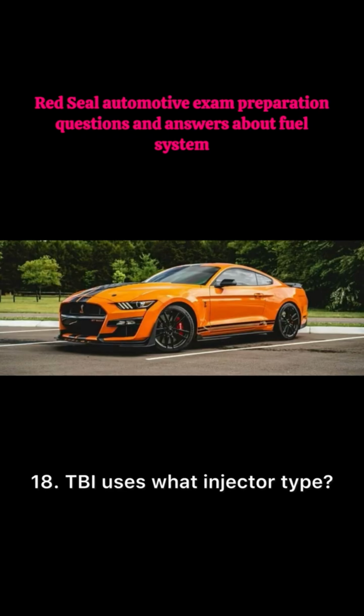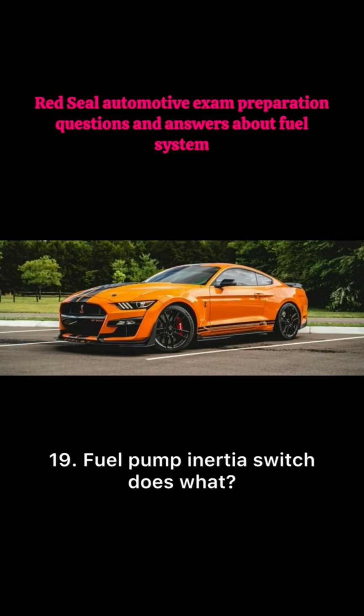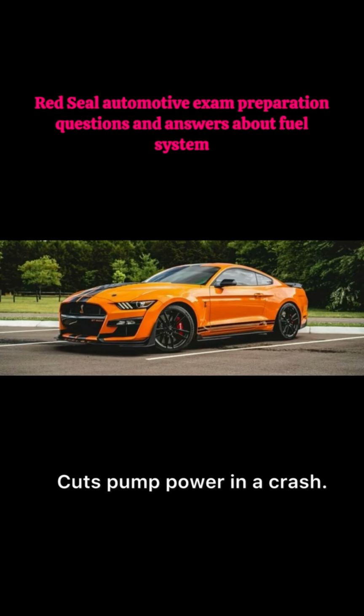18. TBI uses what injector type? Low pressure, high flow injector in throttle body. 19. Fuel pump inertia switch does what? Cuts pump power in a crash. 20. What causes vapor lock? Heat turns fuel to vapor in lines.